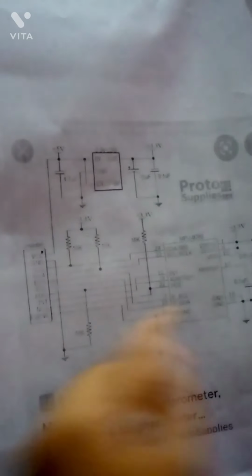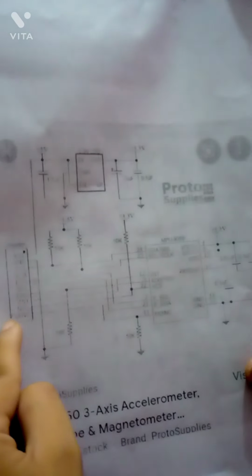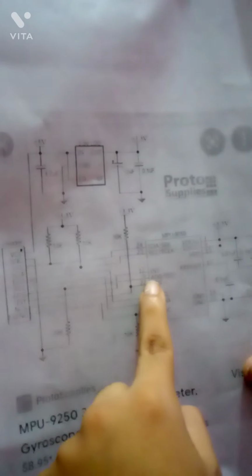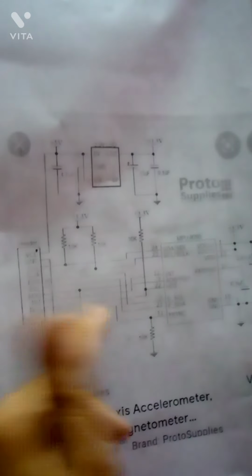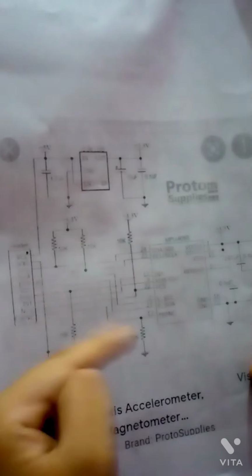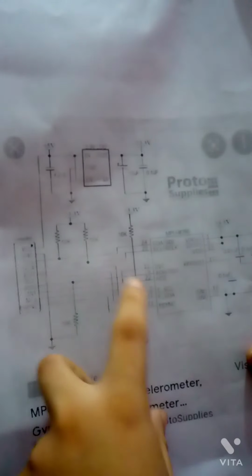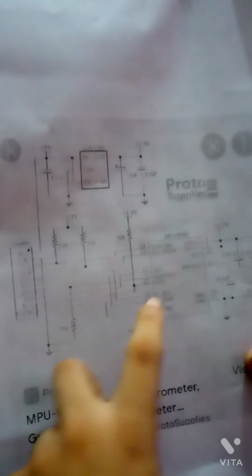There is a synchronized pin which can synchronize the internal feedback, pulled down with 10 kilo as well as pulled up by the Arduino. And there is one more data line, pin number 9 analog 0, which is pulled down by 10 kilo for overvoltage protection. This signal line goes to the Arduino to tell which direction the main motor will be moved. So that's why these wire points need to be pulled down or pulled up for protecting against over voltage. 10 kilo resistors are used to make up clamping for over voltage.